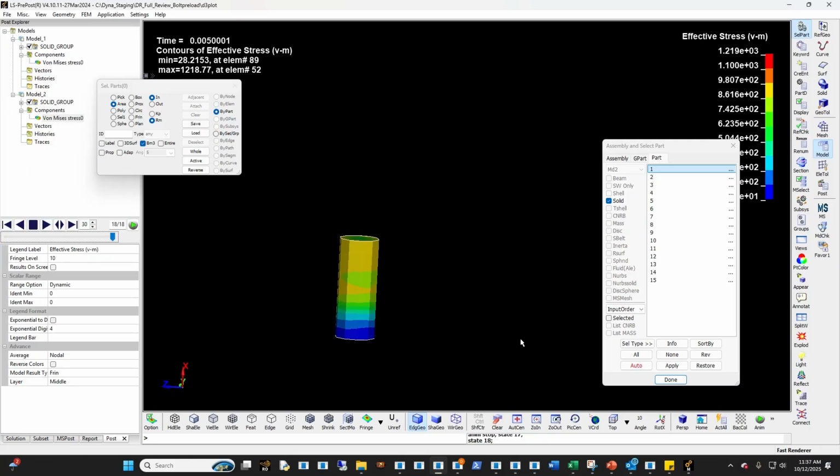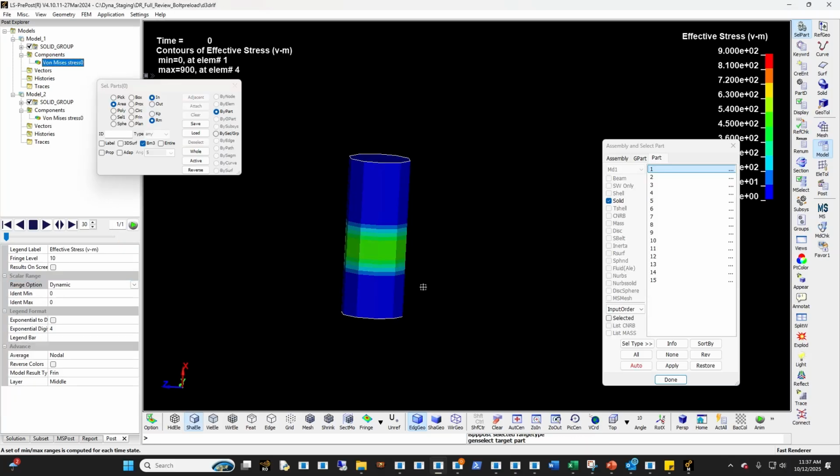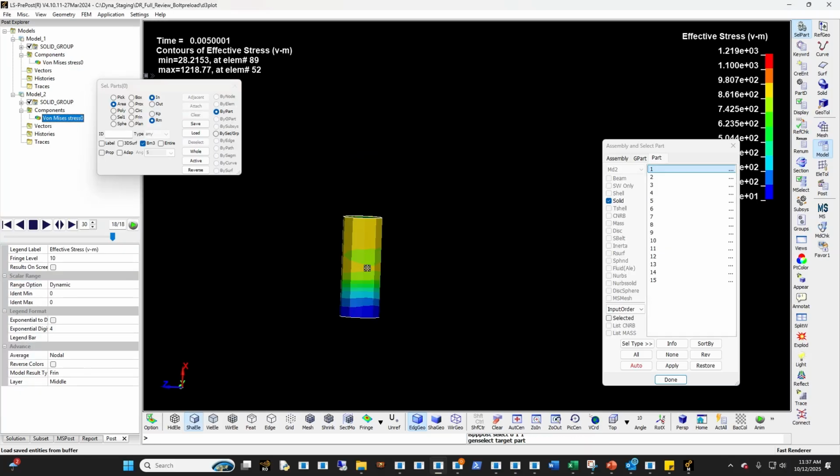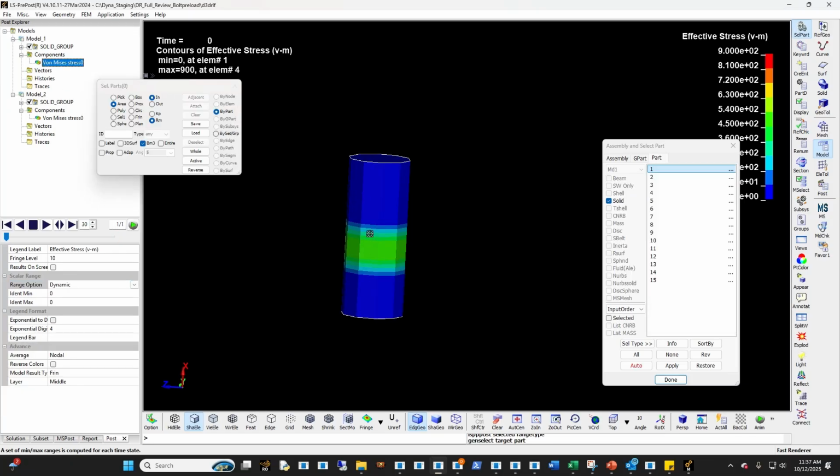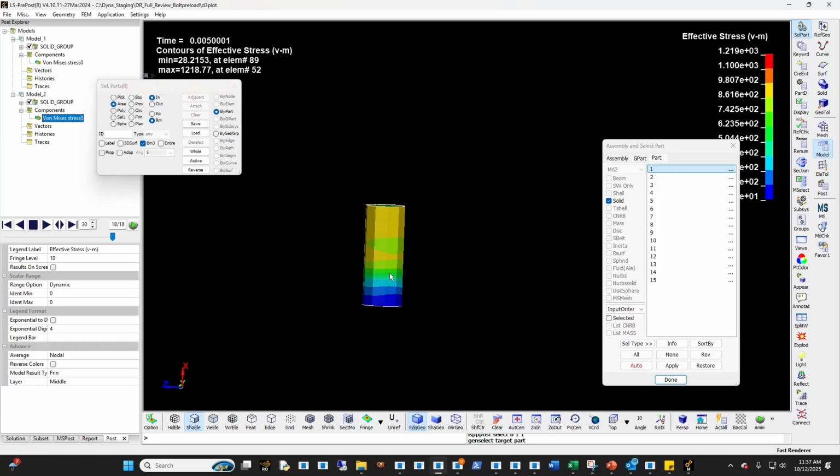The reason the stress here looks a little bit different is because in dynamic relaxation you have a cross-section area that you're applying the load from, which is why it looks like this. But in this case, this is the actual bolt stress in the full transient analysis. This is where the ringing of the system gets removed and you're adding that preload and then killing the ringing of the system. That's all you're doing. Okay, and then this is basically the first example.